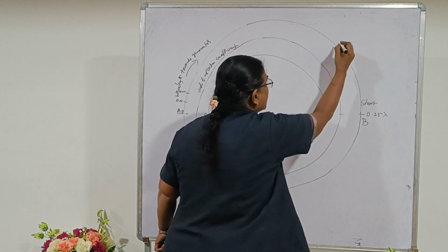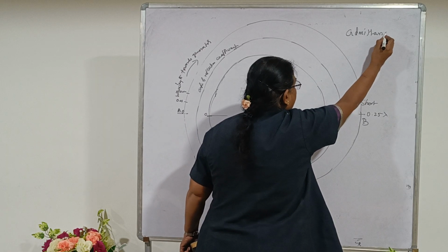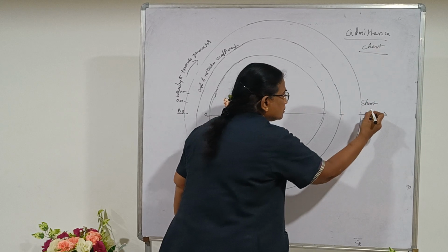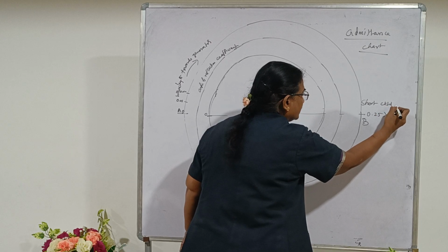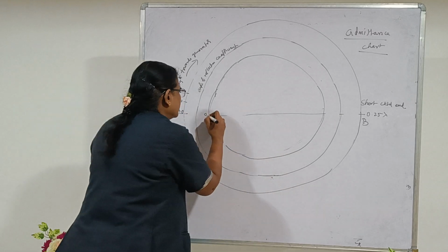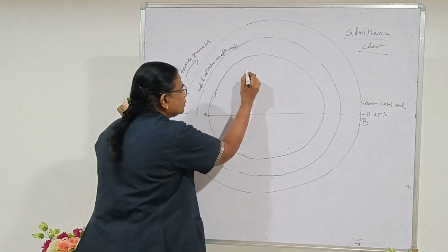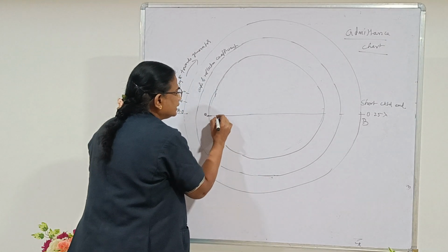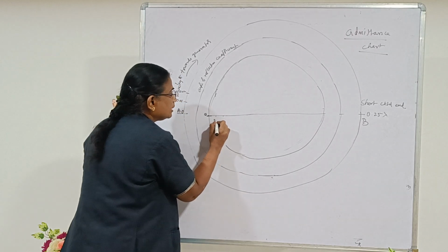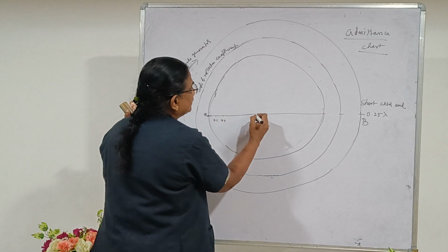We are going to use the chart as an admittance chart. Remember, this is very, very important. Admittance chart. So this is the short circuited end. Here you have the resistance circles. It is R equal to 0, and then R equal to 0.1, like that. Along the horizontal axis you can see the circle values: R equal to 0.1, 0.2, 0.3, and so on.